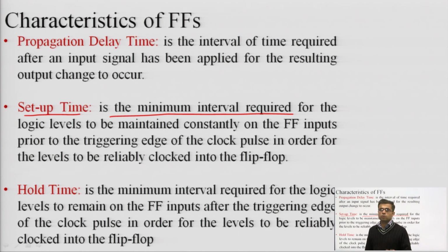So, if I want to apply 1 to the input, I cannot say that I have applied 1 and then removed it. That 1 has to be constantly there, for that amount of time, so that it is reliably fed to the flip flop on the edge of the clock. That becomes the setup time. So, the complete definition is that it is the minimum interval required for the logic levels to be maintained constantly, either low or high, on the flip flop inputs prior to the triggering edge. So, before the triggering edge. It is also known to us that flip flops are dependent on clocks. Without clocks, flip flops cannot operate.